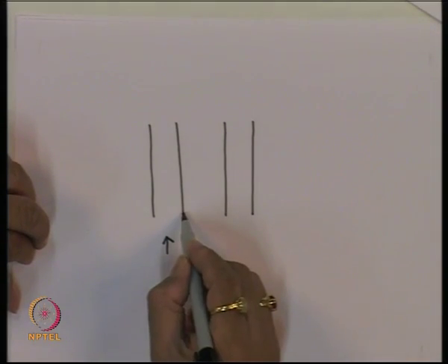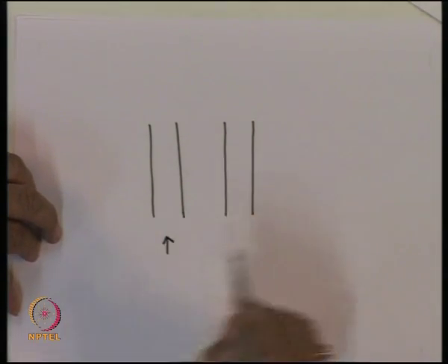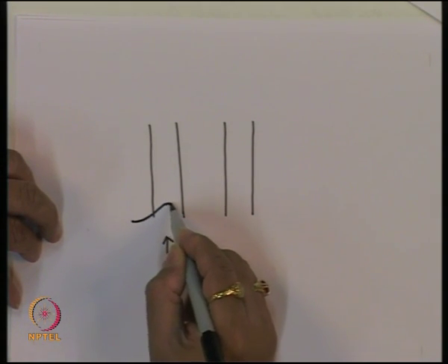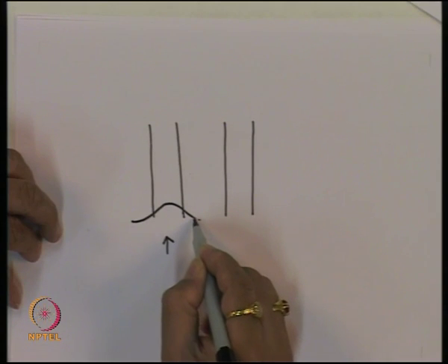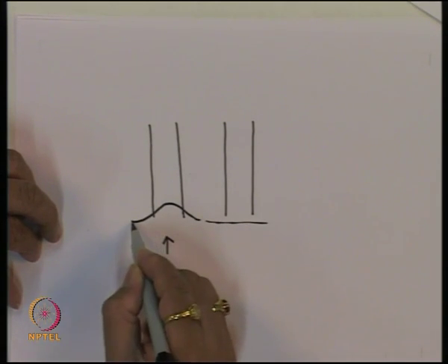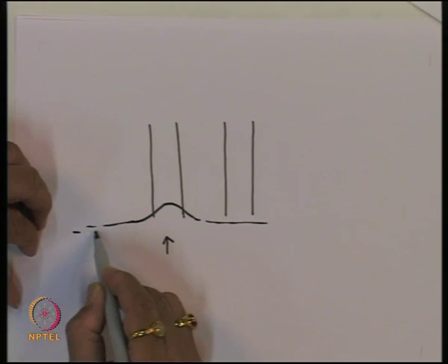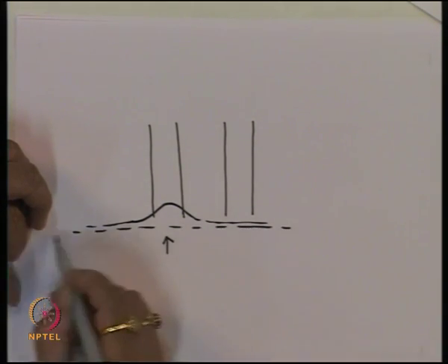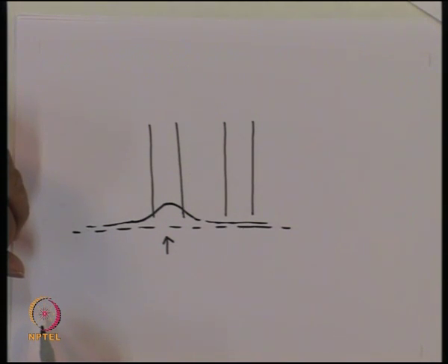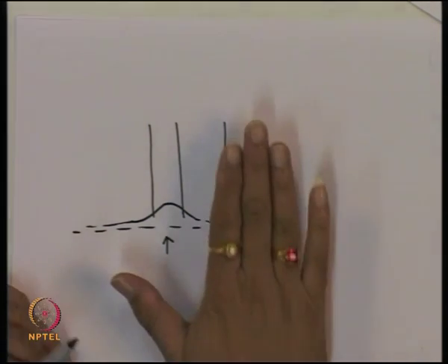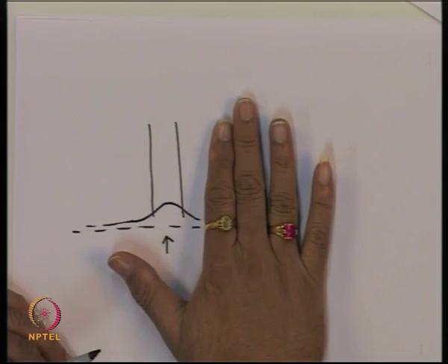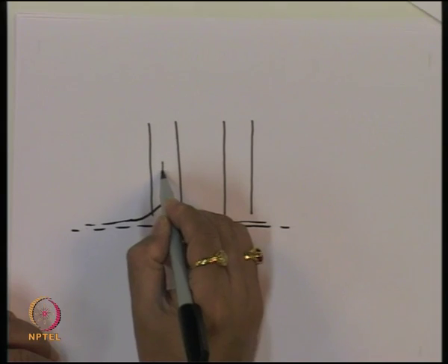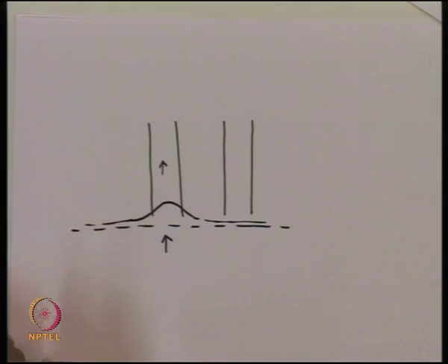When we excite this waveguide, it is going to generate the fields. So it will have a modal field distribution which will look like that, and as we have seen theoretically, this field extends up to infinity, which is the evanescent field. So if the second waveguide was not there, then this field will propagate along the structure with a certain phase velocity.